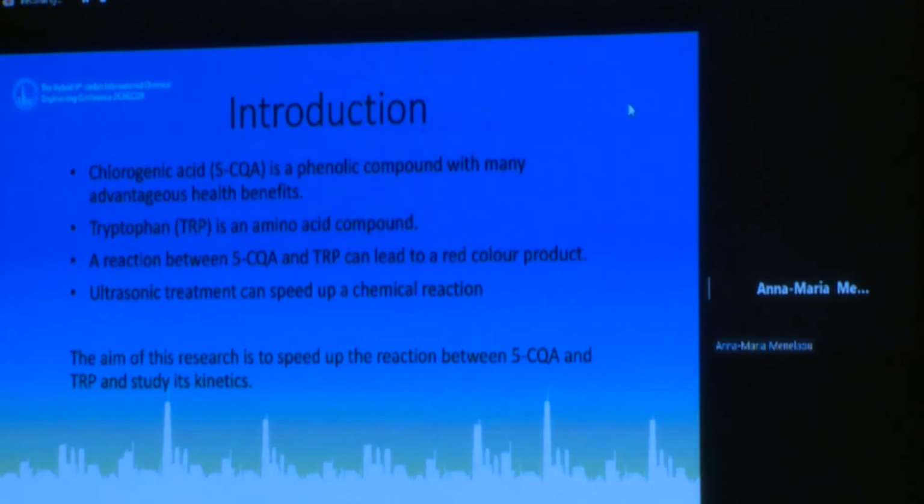Ultrasonic treatment has become a popular method due to its multiple advantages, including reduced energy requirements, waste prevention, and improvement in mass transfer, which in turn can speed up a chemical reaction. The chemical and physical effects of ultrasound are caused by the cavitation phenomena. When the bubbles formed through cavitation collapse, they cause very high instantaneous temperatures and pressure.